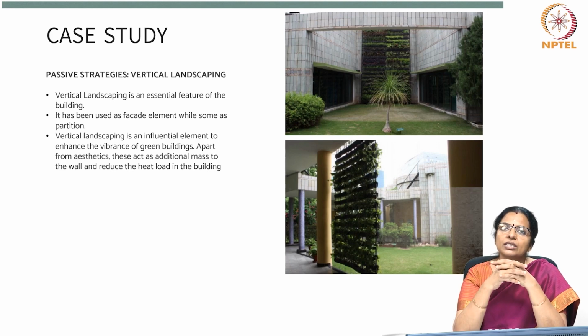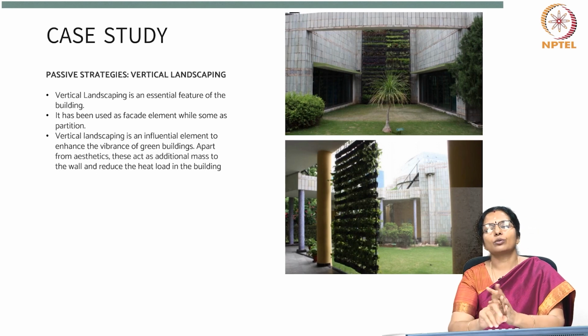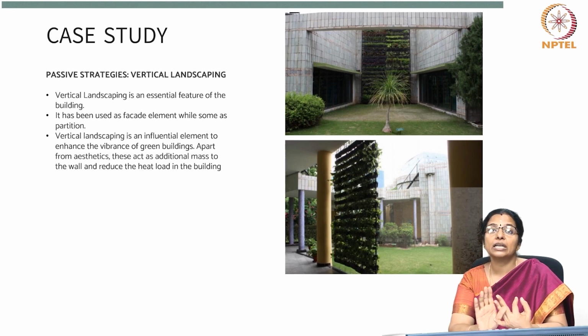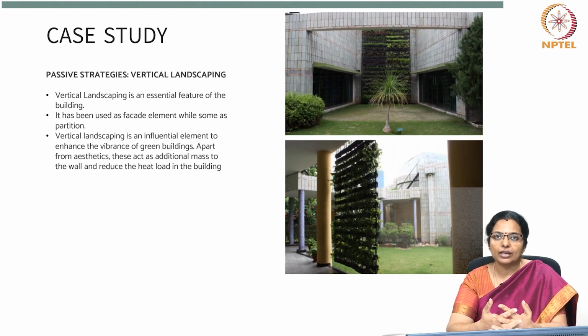This building uses all the simple passive strategies such as appropriate orientation, window size, position, shading of the windows, etc. And some of the advanced passive techniques such as wind towers or green roofs, etc. have been used.